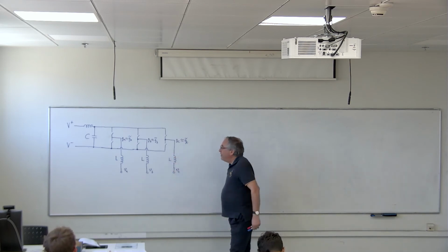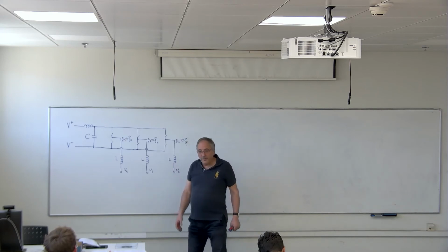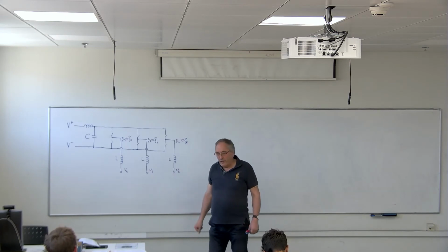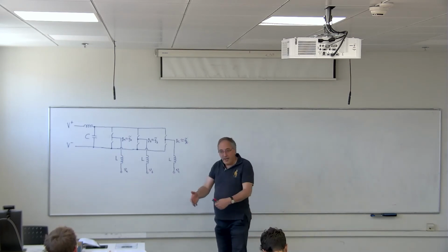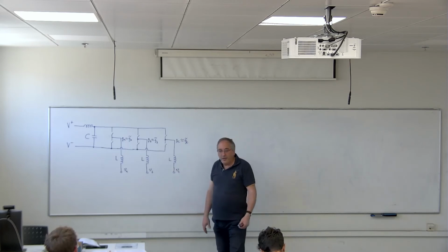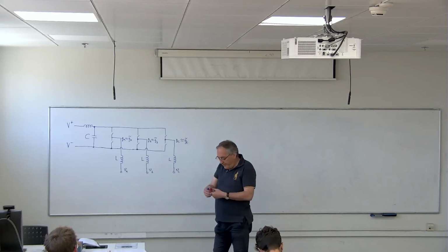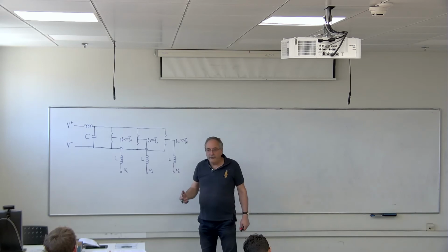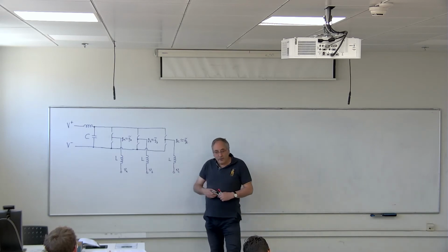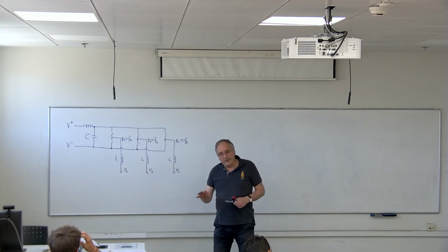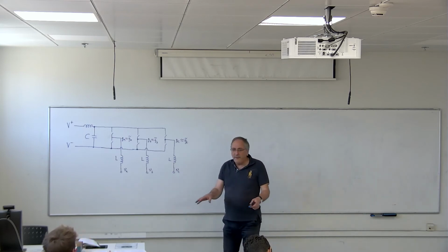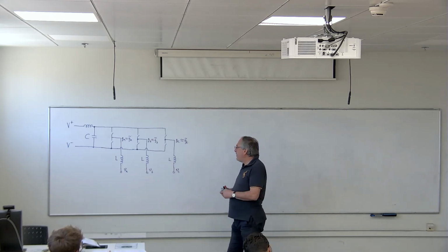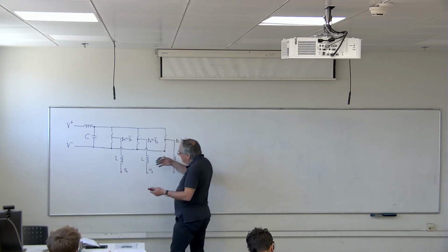But for example, in many inverters, we also want to have a powerful neutral connection, which means a connection to the neutral line of the three-phase grid. I come in a second to why that is sometimes needed, but let's say that that is needed. So we expect strong neutral currents. If we expect only very weak neutral currents or none at all, then we can just work like this.